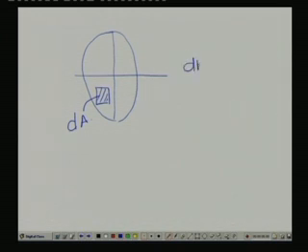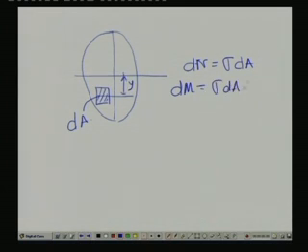So, delta F, if we consider a small normal force, then it was sigma into dA is the force. What is the moment? So, dM, the amount of moment generated, because this is at a distance y, becomes equal to sigma dA into y. So, what is the total moment generated over the cross sectional area? That is the integral over the area A of sigma dA into y.